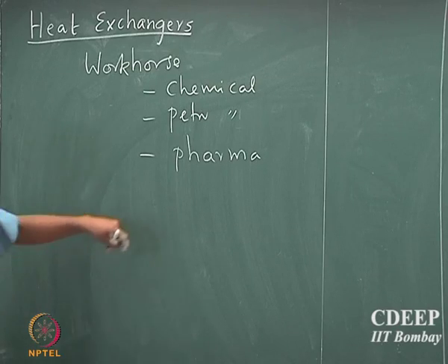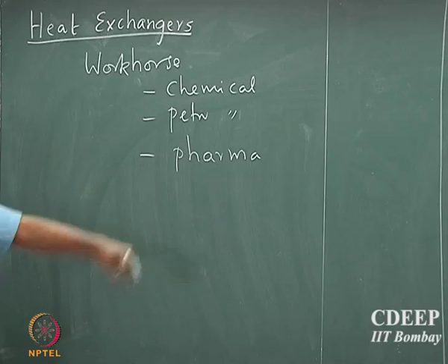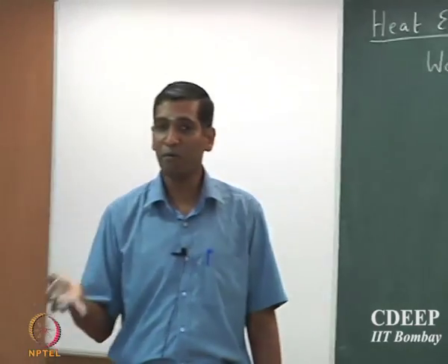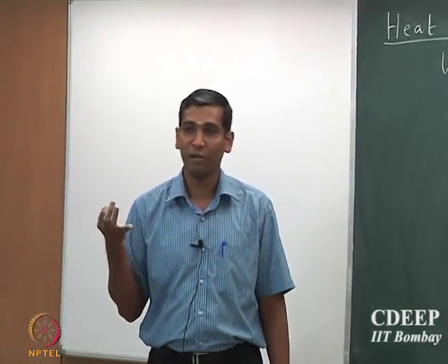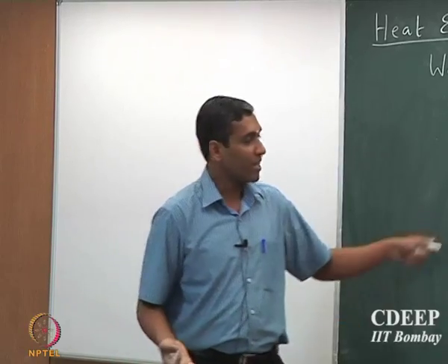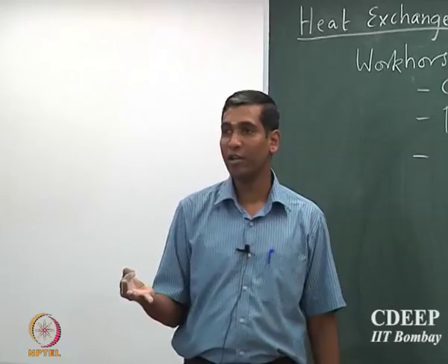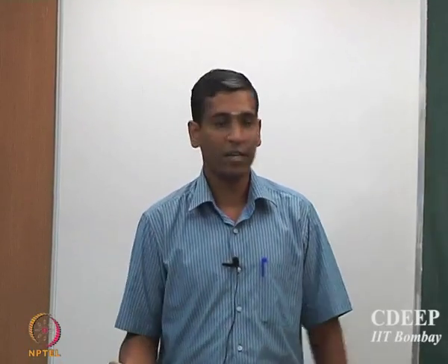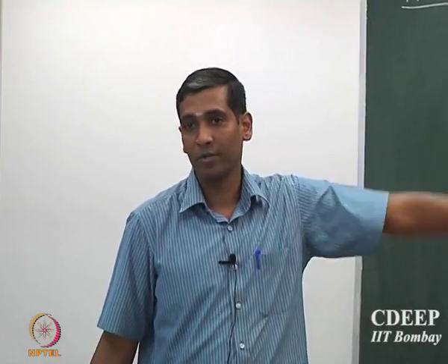So really in pharmaceutical companies, it plays a very critical role, because the precision with which you want to make the drug is significantly high. You would never want to sacrifice on the precision of the composition of the drug. So the temperature of the material which is going into the reactor to get converted into the drug plays a very, very significant role. So heat exchangers and precise design of heat exchangers and efficient use of heat exchangers play a very important role in pharma industries.